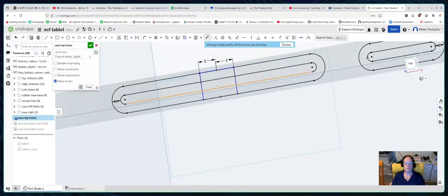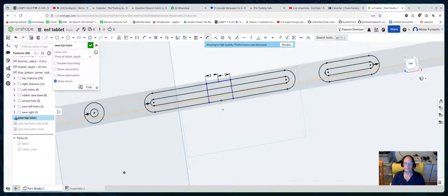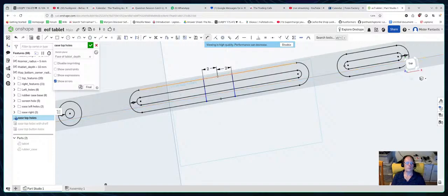Great, so this is going to be like the pivot, a 4mm thick pivot extrusion, which we're going to keep in the case. And then we want to actually get an offset, maybe a 0.5 mil offset in here. Let's do that. Let's just do the whole thing magically.